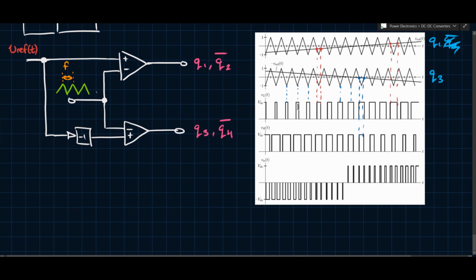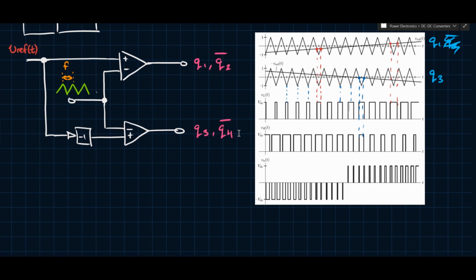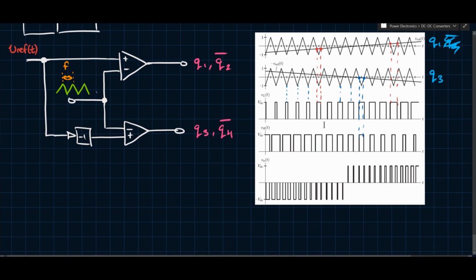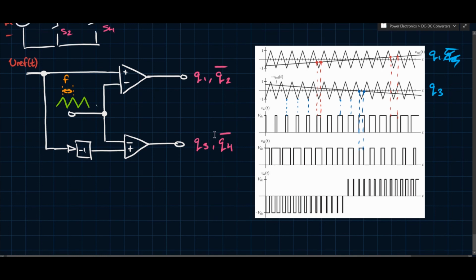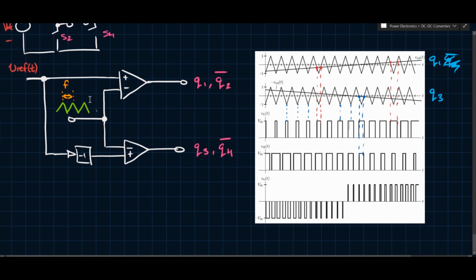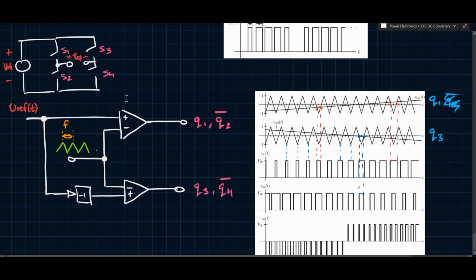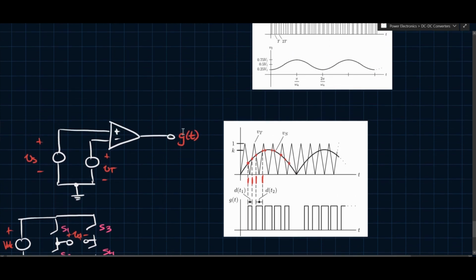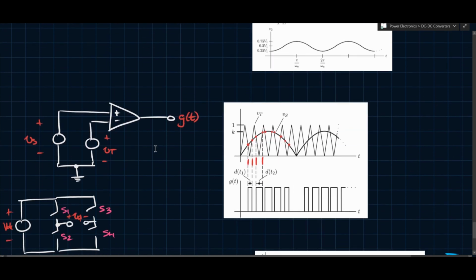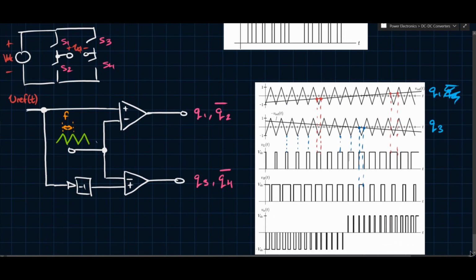So we've seen here a way to generate this. And again, there are more elaborate, more complicated ways of doing it. But essentially, this whole process that we see is repeatable for any converter. This is not unique to a power converter. You can apply this to any topology as long as you know which switch should receive which pulse and what the output waveforms look like. So this is a universal technique, and this is not limited to the buck converter or to the full bridge. So please don't assume that they are.